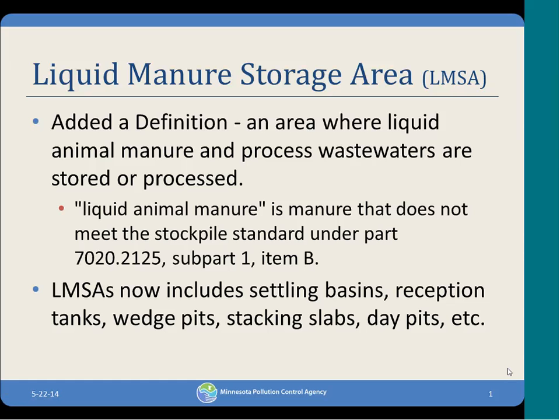Basically it's the standards. I don't think it's much different than a normal floor. We just want to make sure that they call out that it's a type 3, that they're doing the reinforcement under where that wall is going to be, and that they are meeting standard for the concrete, because those panels come in precast. So we don't want the floor to be precast as well. We want to make sure they're calling out a type 3 floor. We can email out that standard so that you have all the verbiage if you need it.